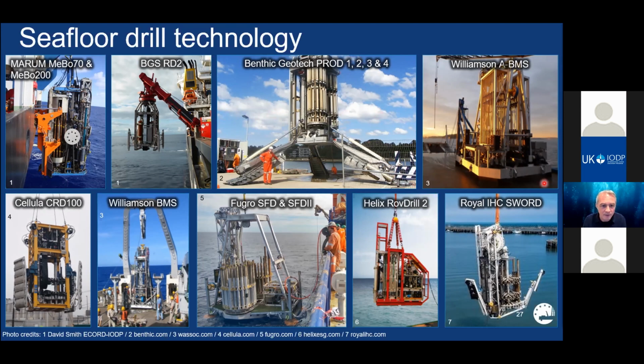The concept of these drills is relatively simple. These are mobile drills lowered to the seabed using an umbilical that carries the power, the communication and the control. Then the drill pipe, the core barrels and other tools are manipulated to and from a carousel or magazine using robotics. An onboard top drive provides the rotation for the coring, and an onboard mast feeds the drill pipe into the seabed.